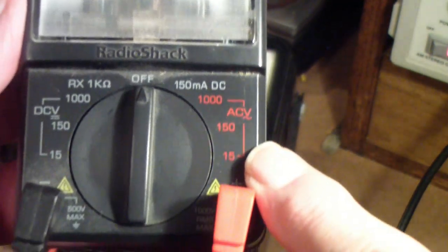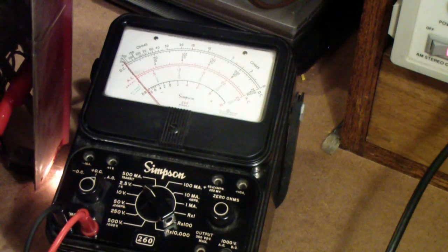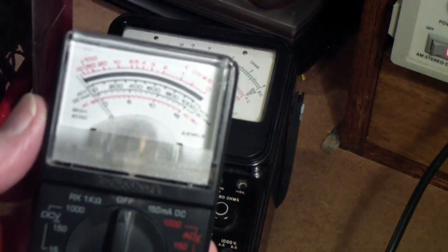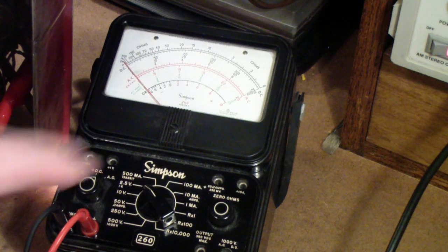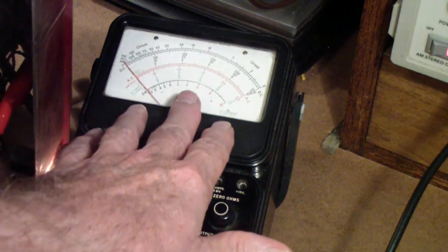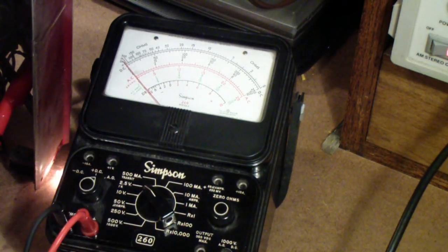You see that over here. Well, 15 volts is not sensitive enough to really do this kind of alignment. So unfortunately, I wish I could recommend that you buy a nice cheap meter like this as your second meter. Unfortunately, they only have that 15 volt range, and by the way, that has to do with the quality of the meter movement itself. At some point, you just run out of sensitivity no matter how you rearrange the circuitry.